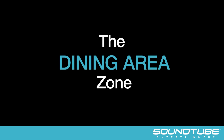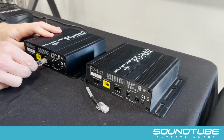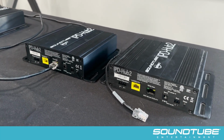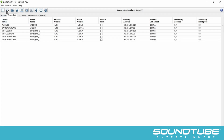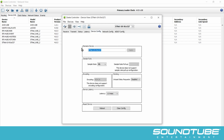We're now ready to set up our dining area. This area will have two IPD-Hub 2s, so we'll start by connecting the first one. Once connected, we will again rename the device within Dante Controller by double-clicking it, going to Device Config, and giving it an appropriate name for the zone. We'll call this one IPD-Hub 2 Dining 1.